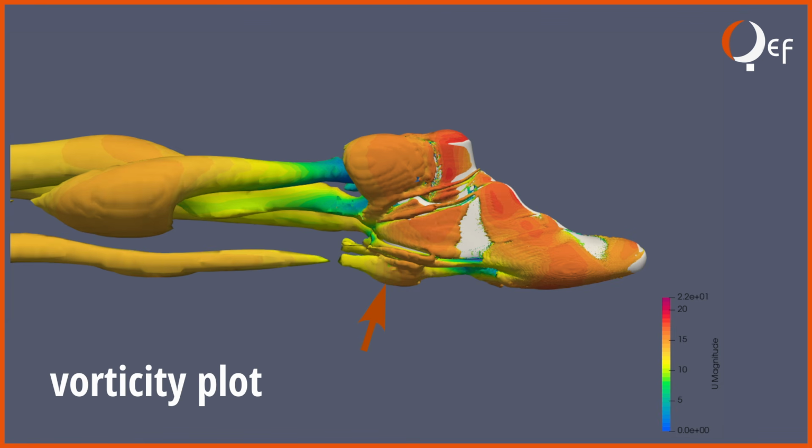On the sides of the shoe, the separation of airflow generates the major part of the wake. The separation point occurs late on the left and right side surface, causing the wake to be narrow. We can conclude that even though the shoe is a bluff body, its frontal superior surfaces are quite aerodynamic.